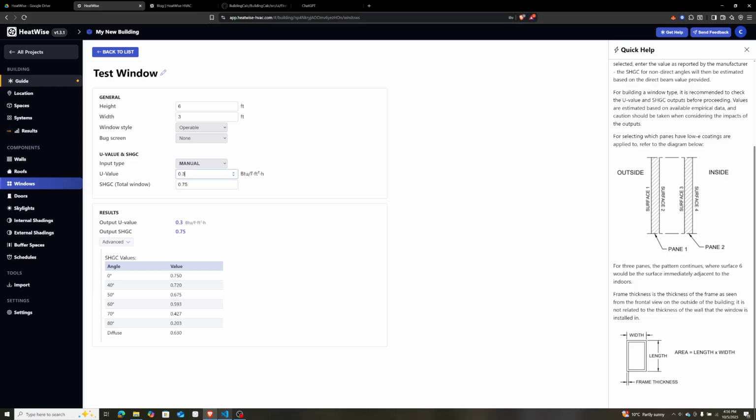The U value is much easier to find, but you just need to note whether it is the center of glass U value or the entire fenestration product U value, because that U value will actually change, not just including the frame, but on the glass portion getting close to the frame. You have your center of glass value and an edge of glass value and then a frame value, and it will change with the dimensions of the window. As you have a more elongated window, you have a higher portion of frame and edge of glass area.